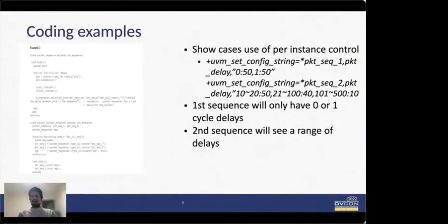And basically by doing the uvm_set_config_string and also providing the full path while calling the actual get_run_val, this is where some of the extra optional knobs come in really handy. If you want to use the uvm_set_config_string, you need to provide a path so that the code recognizes it and processes it using the set config string instead of passing it as a plusarg.